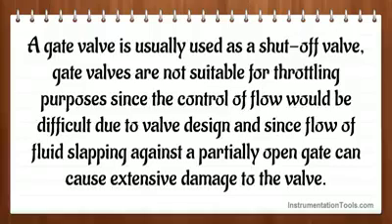A gate valve is usually used as a shut-off valve. Gate valves are not suitable for throttling purposes, since the control of flow would be difficult due to valve design, and since flow of fluid slapping against a partially open gate can cause extensive damage to the valve.